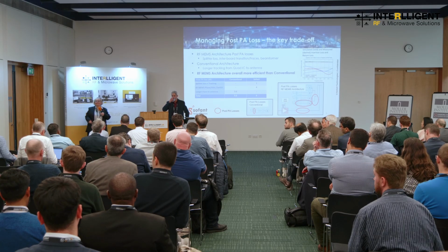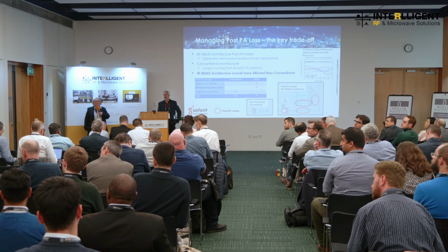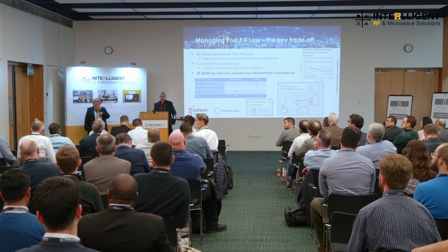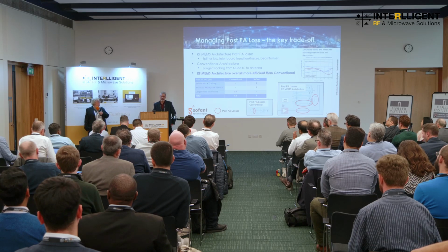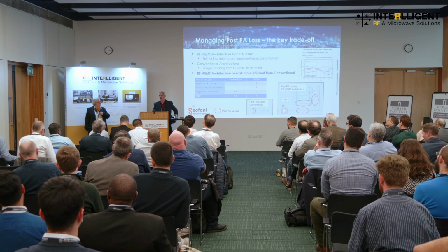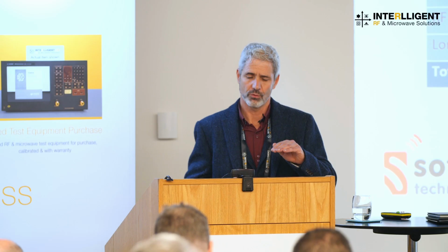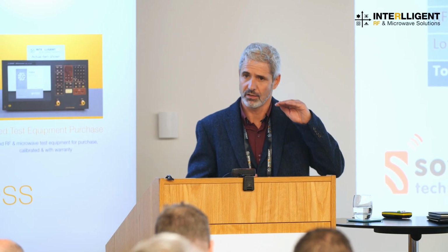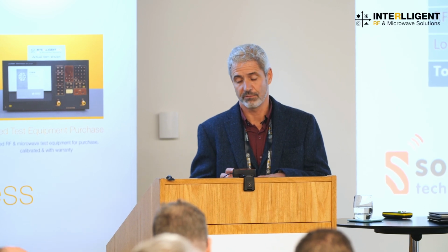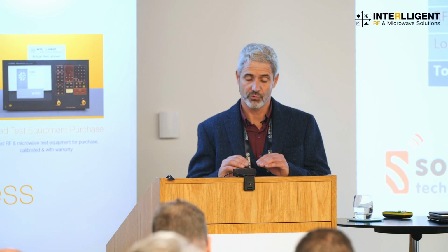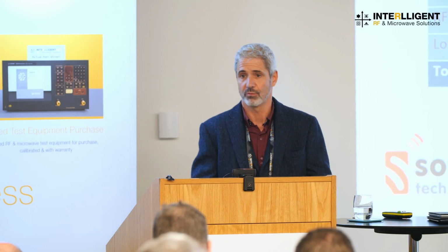Okay, just one more then. A quick question. Are the switches affected by the power of the signal? No, the MEMS is very, very linear. In fact, it's very difficult to measure the linearity because that's one of the inherent advantages. We've designed the current MEMS bridges for a certain power level, but we've looked at much, much higher power level devices, so they're not affected by it. The thing you have to worry about is if you don't design them correctly, you can get RF self-actuation. That's probably the biggest issue. But in terms of linear performance, they're extremely linear.